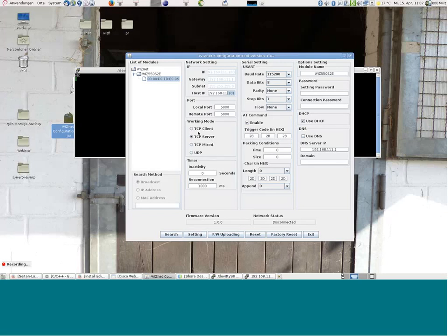And you can do the same serial to Ethernet without IP connectivity with UDP. Just send data to this IP address, the 183, and this data shows up on the serial side and the other. Then, to keep such a connection alive, especially if you are a client, we have an inactivity timer and a reconnect time to keep a connection established.